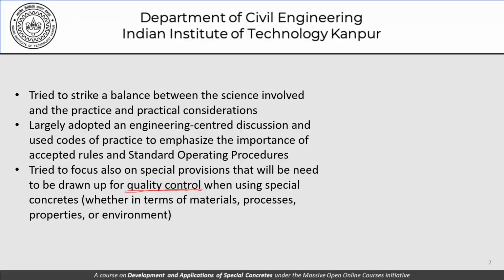You will recall our discussion that we had in terms of preparing panels for shotcrete in order to get samples which can be used then for determination of compressive strength, or collecting the samples of underwater concrete in a tank of water. So these are the kind of special conditions that need to be incorporated in our testing mechanisms or testing systems, and one should not be afraid of creating new SOPs if the situation so demands.